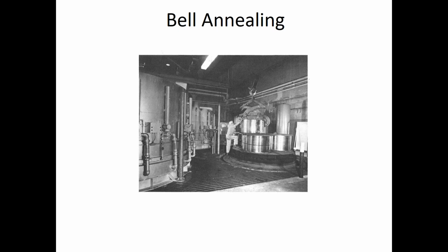There will be an atmosphere added so that the coils don't tarnish. It will be heated up to a certain point, and because of the quantity and mass of the metal, it has to be heated for a certain period of time to allow every bit of that metal in that furnace to relax, anneal to the right level. And then the furnace is opened.